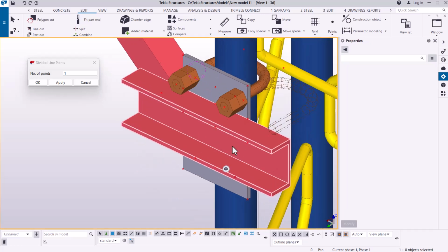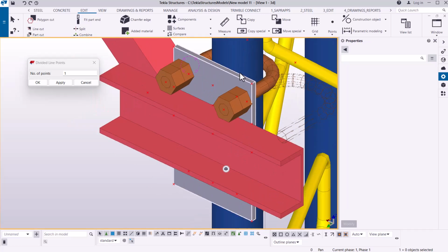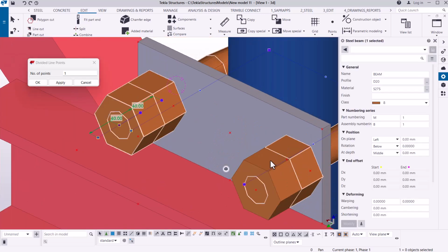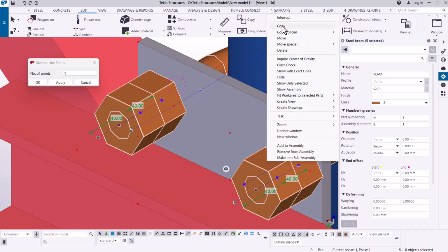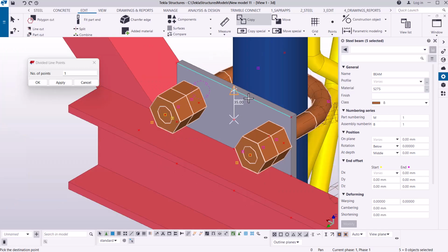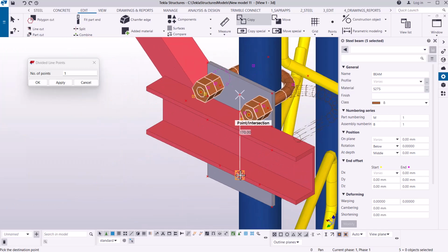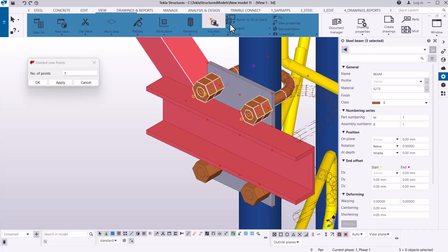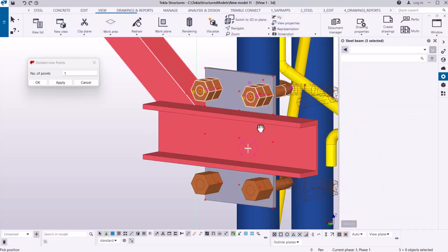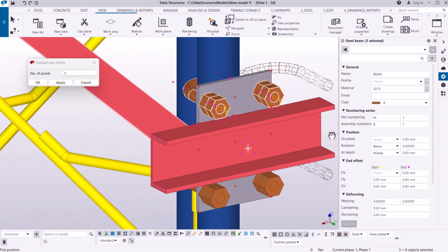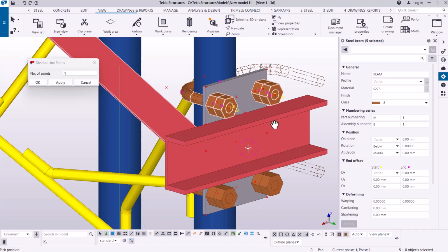The same thing I'm going to do is to copy this member. Select on that, press Control, select that, select this, select that, then right click and come to Special Copy. And I want to copy it from that center and bring it right to that center. So let me check whether we've done the right thing. I'll come to New and come to Navigate. Remember, you can press Control and rotate that. So you can see we have that in place. So this is just to grip this, and this member will be welded on the plate permanently.